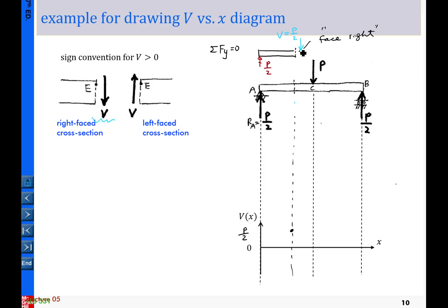And this is a shear force, so I use V here to indicate a shear force. The next step is, based upon the calculated result, to check with the sign convention. For this case, downward is positive, so that means I put this point as positive in my shear diagram. And from here you can see, if you keep changing the sections, as long as it remains between A and C, that reaction should be constant throughout the selection in this segment.